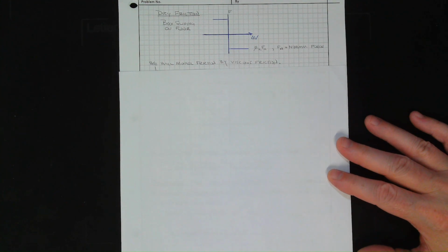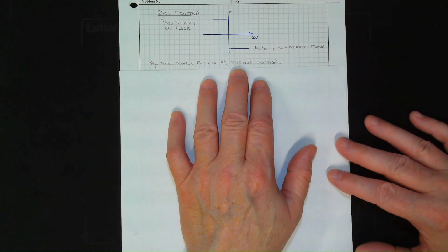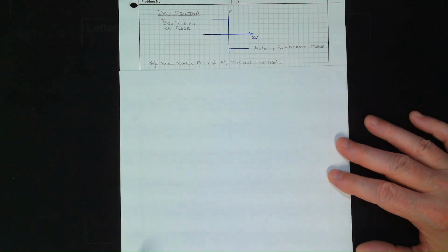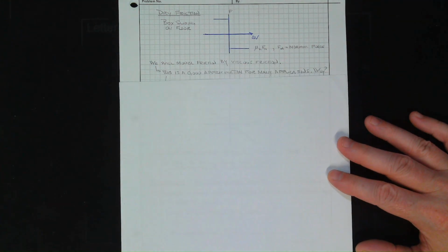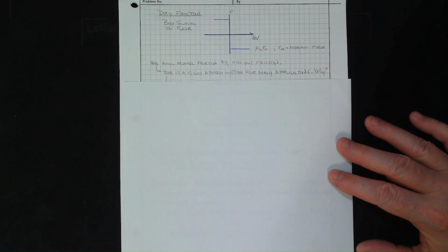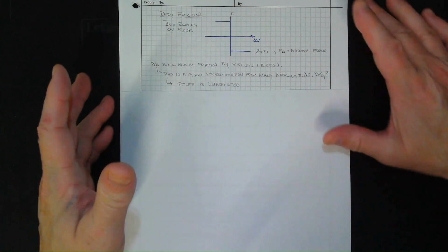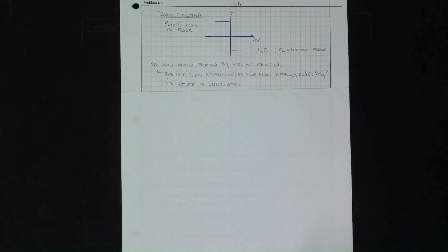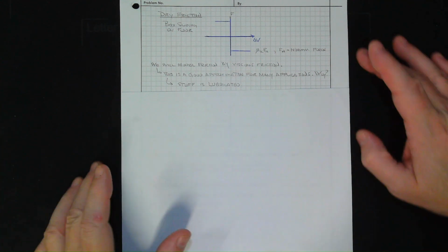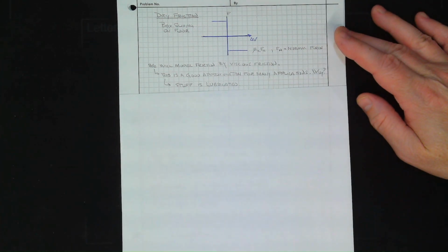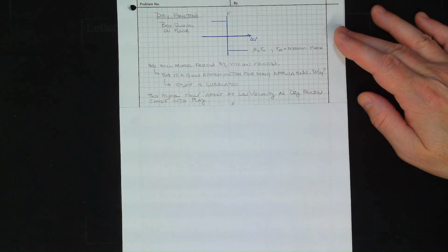And as I said, we are going to tend to model things by viscous friction. You may go, well, why didn't we use this one? Well, because we're looking at machines. And here's the thing. When you're looking at machines, most stuff is lubricated. All right, you're not usually going around sliding boxes on floors. So we're dealing with purposely designed systems, and so they're not going to tend to have dry friction so much because they'll have some sense of lubrication. So the viscous friction will work for us.